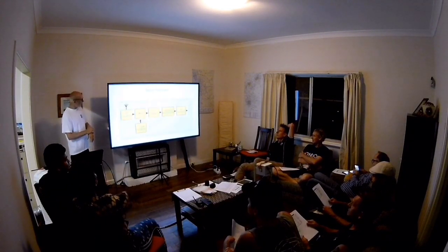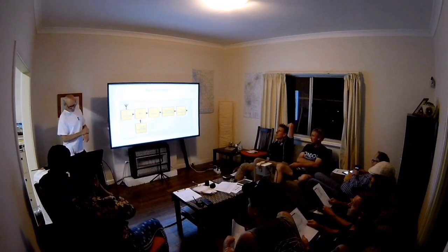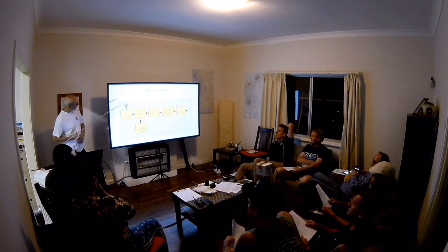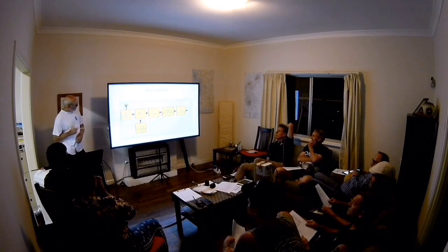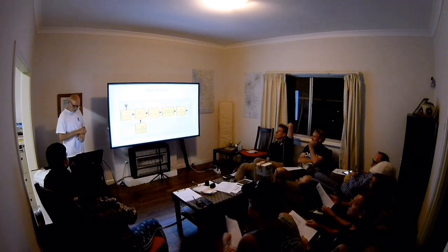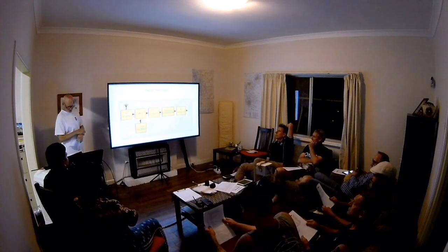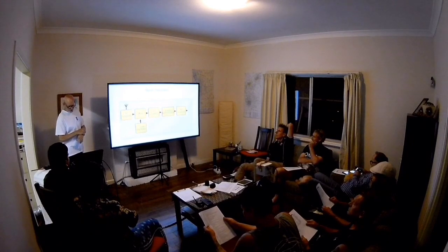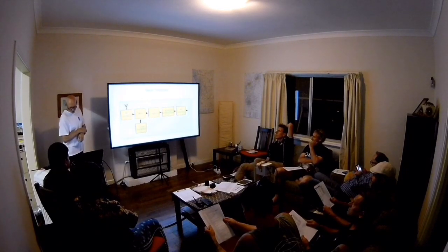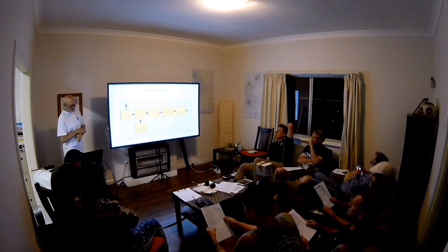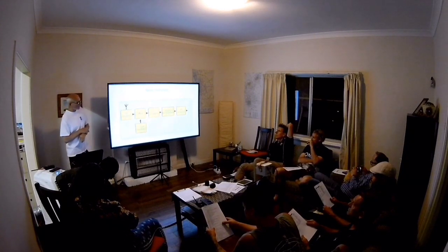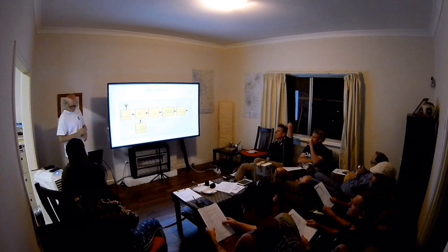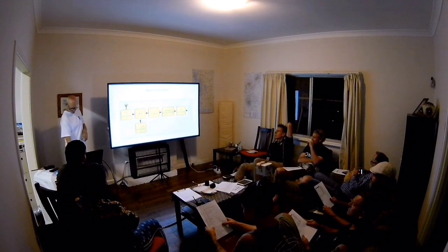So here we have a diagram of a basic receiver. You have the aerial, this is an aerial here, which goes into the RF amplifier, and a mixer with a local oscillator feeding into that. That is then fed to the IF amplifier, which then goes to the detector or demodulator, and then onto the AF amplifier, and finally out the speaker where somebody's voice appears. All instantaneous, amazing.